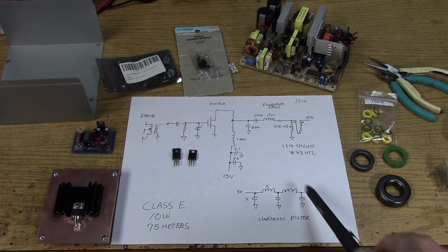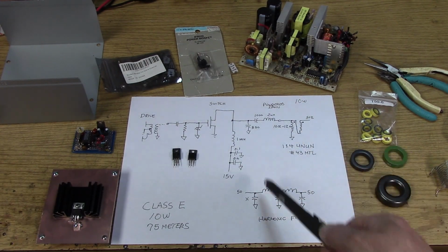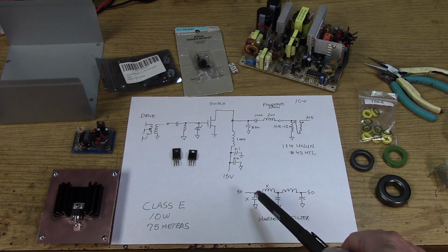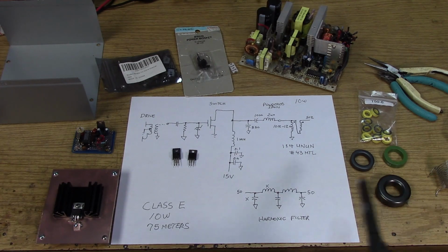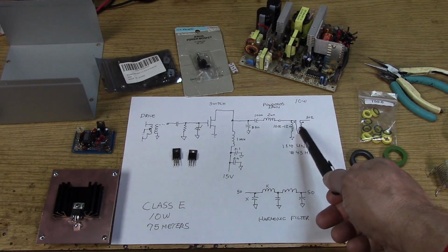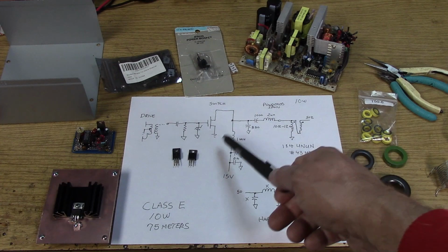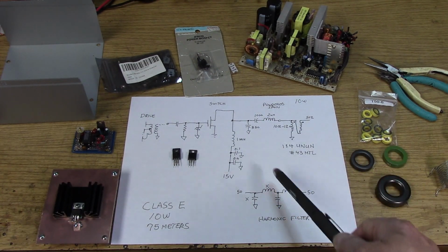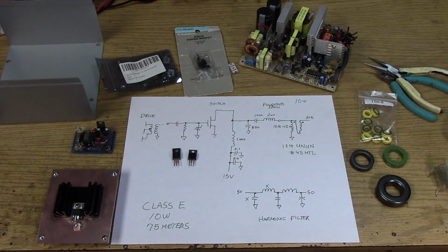So there's a lot of flexibility here, and I wouldn't need to use a balun. I could do it all just with this section here using matching techniques, LC matching techniques. But I do like the idea of using the broadband balun because it's going to add stability to the stage. So we would end up with this circuit with this tacked onto the end to give us the harmonic rejection.